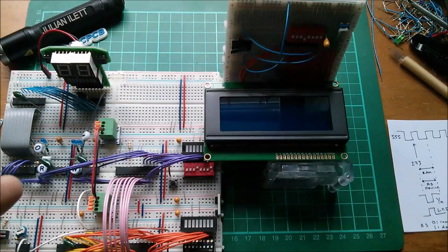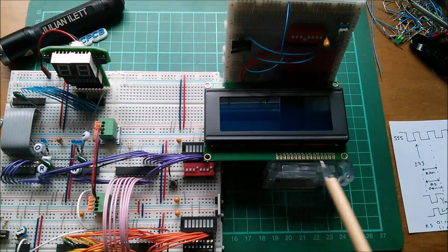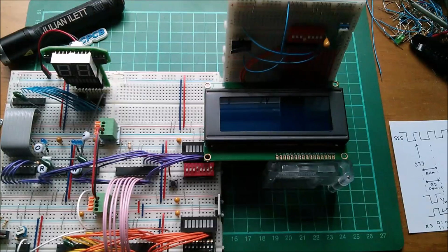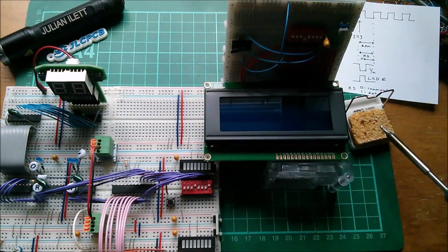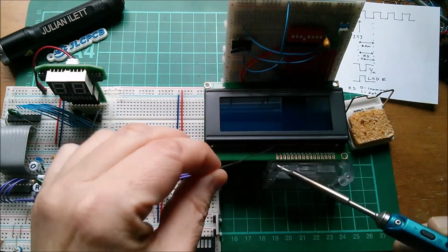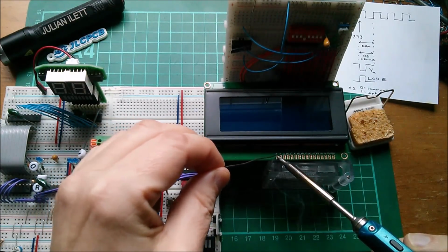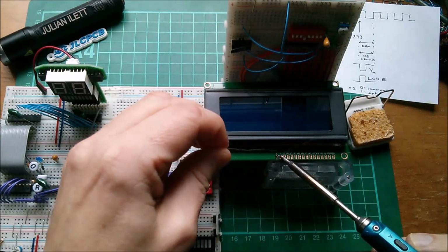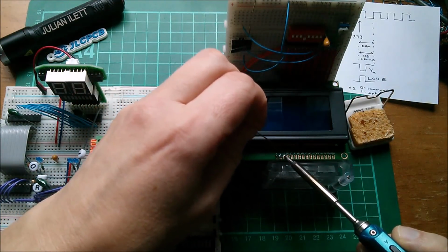Another day of not wonderful lighting. So I balance this here. I'm just going to solder all of those so that the display and its connectors are as one. Right, iron is up to temperature. Bit of a clean up on the sponge. And then let's run across all of these, including the cathode and anode. These are gold plated, so they're taking a little bit of solder to take.